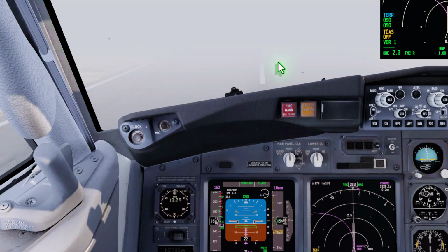Now with this, gang, once we touch down, remember I talked about in a previous lesson, you could have a slight crosswind crab in this condition, because the airplane has a capability of landing even Cat 3 in a crosswind condition, with limitations which generally is around 10 knots. May be different at different airlines.